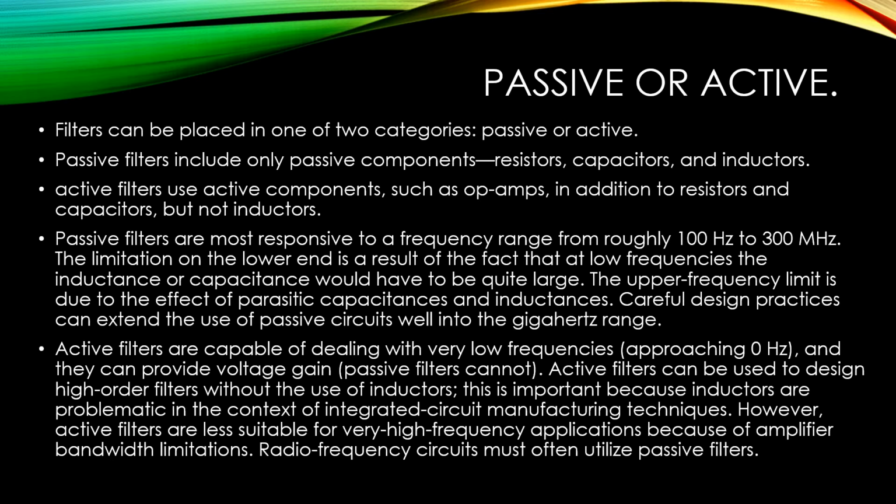Active filters are capable of dealing with very low frequencies, and they can provide voltage gain. Active filters can be used to design high-order filters without the use of inductors. This is important because inductors are problematic in the context of integrated circuit manufacturing technique. However, active filters are less suitable for very high frequency applications because of amplifier bandwidth limitation. Radio frequency circuits more often utilize passive filters.